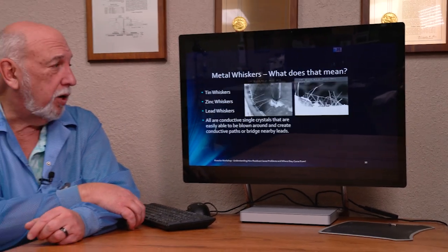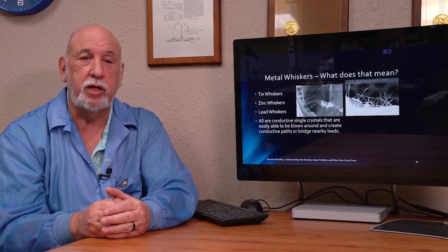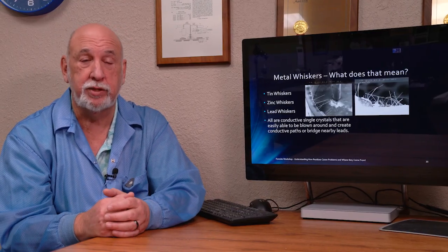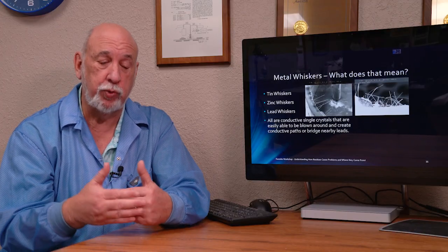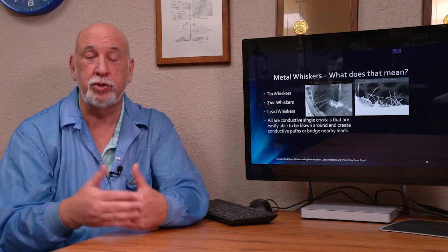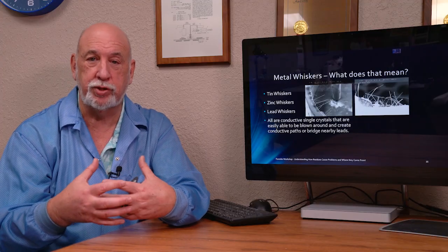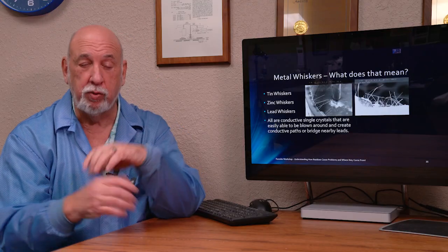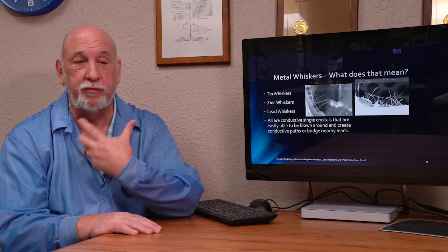And metal whiskers. Everyone has heard about tin whiskers. We've also seen zinc whiskers. We've also seen lead whiskers on high lead content solder. But tin whiskers are the biggest concern that the industry had when we made the switch to lead-free alloys. Having a small percentage, 3% lead, does a great job of reducing the stresses internal to the solder material, and you have less whisker formation, either solder or plated. We have a lot of tin plating.